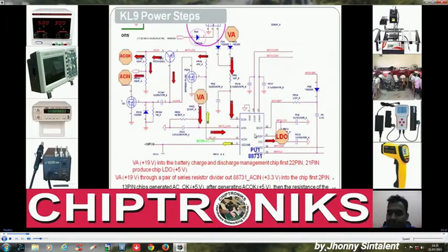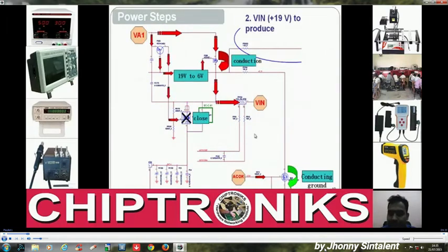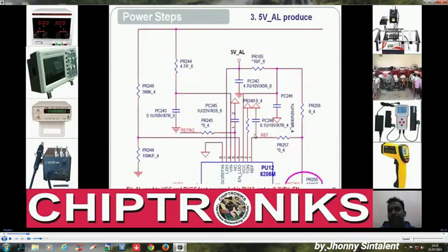These things we already covered in the previous class. So till the previous class we have discussed the generation of V-in in Lenovo Y570 and DC bat out in DB2000. So let's refer to Lenovo Y570. V-in is generated, and V-in goes to pin number 6 of RT8206. This is the first step.